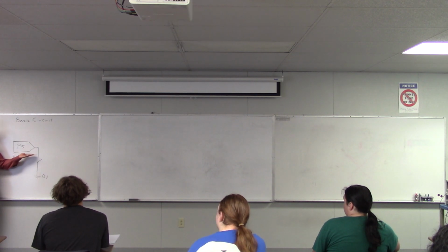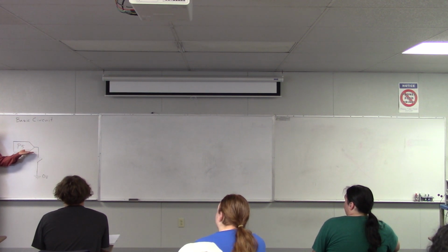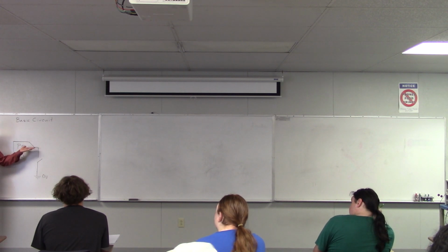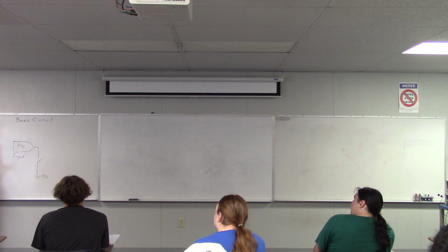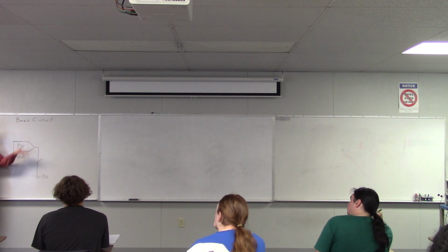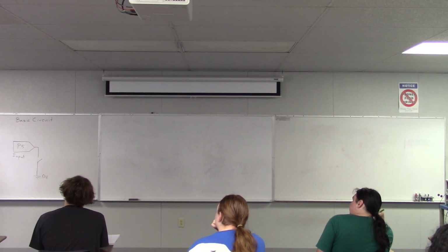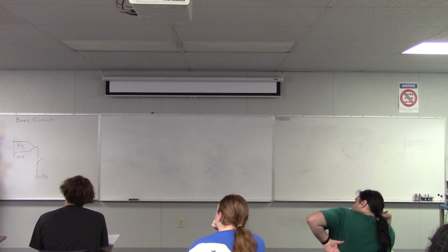It could be 0 for some of the time, but there's nothing holding it down to 0. So it could also kind of float up and be 5 volts for some of the time, depending on if there's static electricity nearby, or somebody walks by and brushes against it. So it could go up to 5 volts, it could go down to 0 volts, and it can float around and change those voltages, go to high voltage or low voltage at unexpected times without really any way of knowing when that's going to happen.